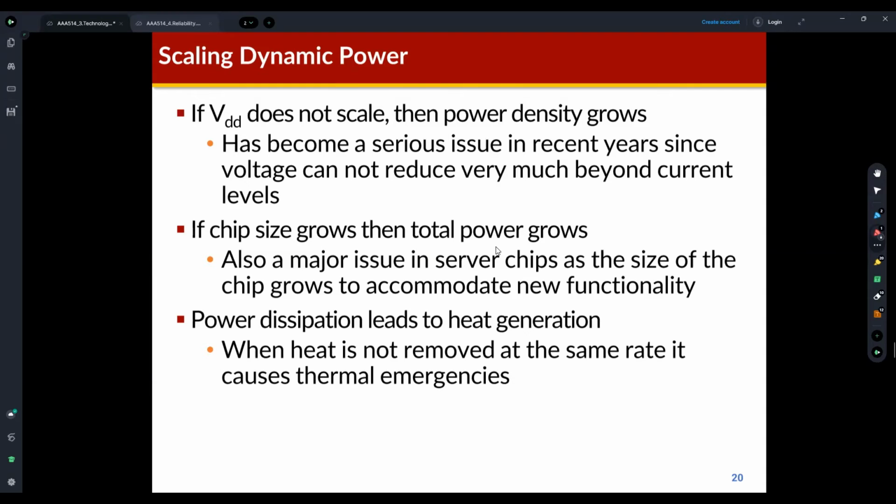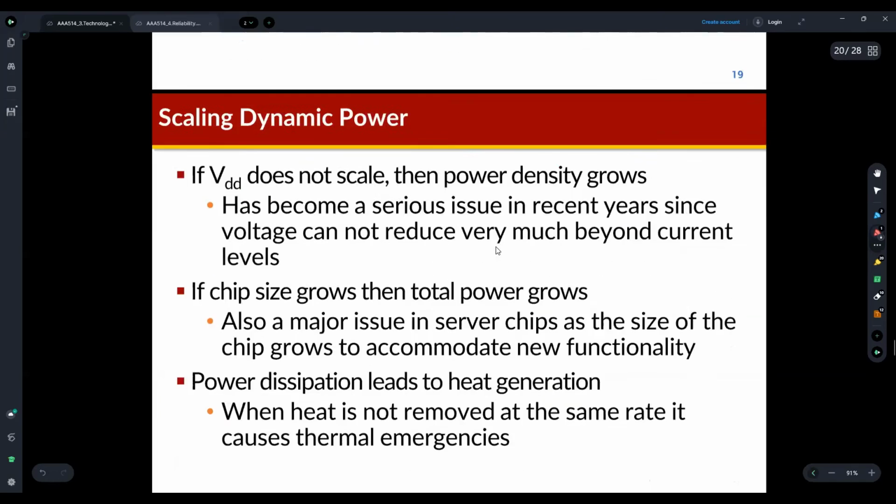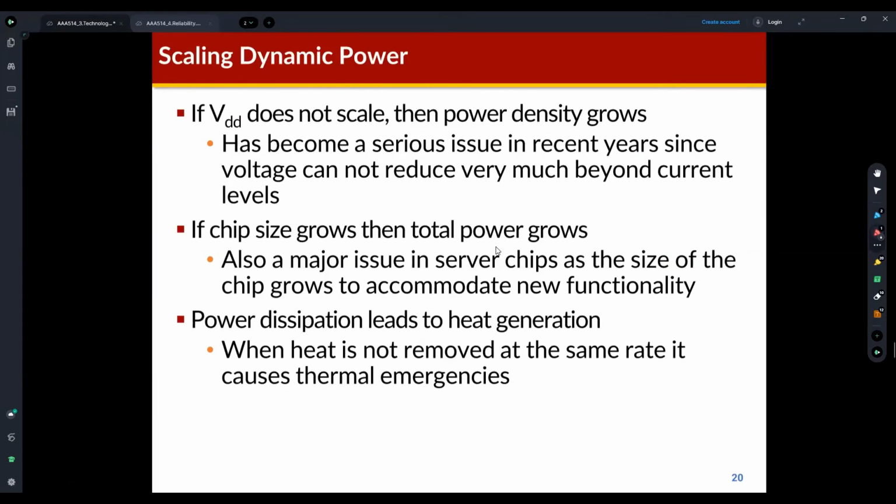we can also think about some other factors, okay? So in this equation, the Dennard scaling, just to assume that we can scale down the C and VDD, also we can scale up F, and the chip area is the same. So power density is the same. The Dennard scaling just explains the power density per unit area. But think like this.